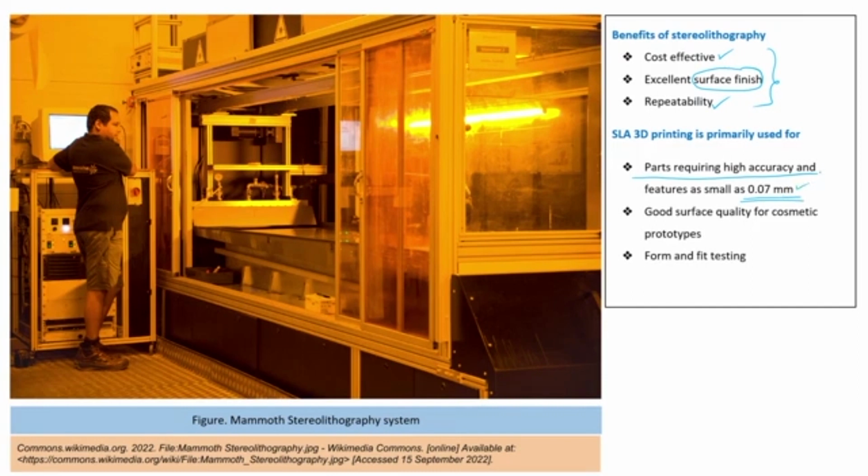It is very small, 70 microns part size can easily be manufactured, which we have already seen by using projection based techniques. Good surface quality is achieved for development of cosmetic prototypes. When we want to realize the design at an early stage, we have to generate the prototypes and their surface quality is in an acceptable range.